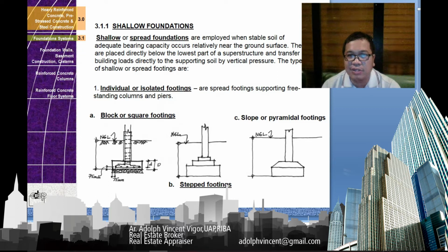So shallow foundations are employed when stable soil of adequate bearing capacity occurs relatively near the ground surface. This is the common type of foundation that you're going to see and encounter, class, throughout your practice if you're just going to do residential designs.